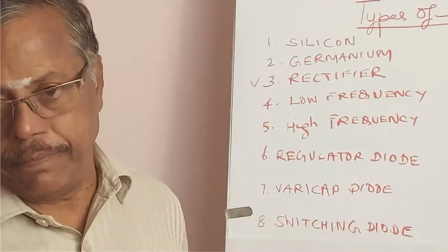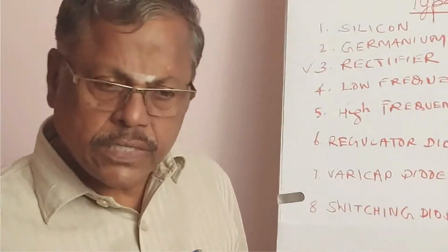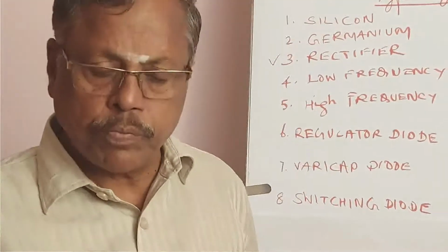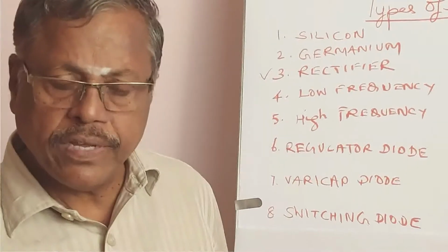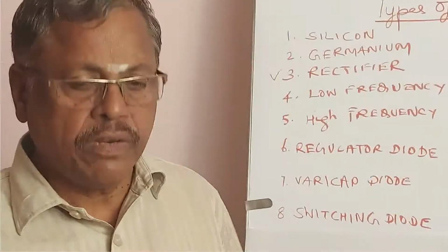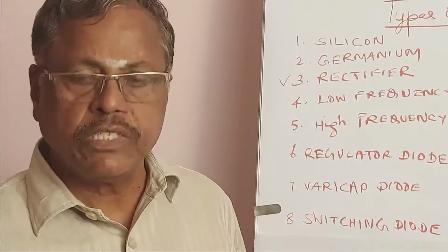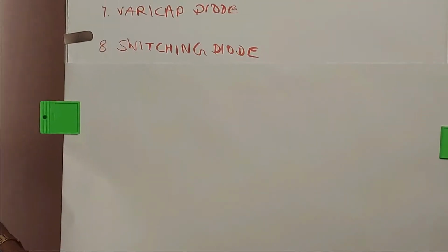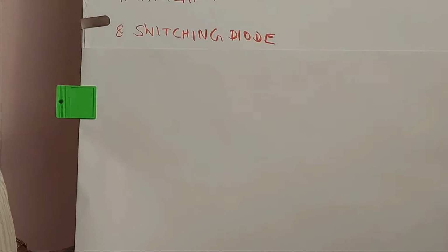They form a capacitance. Every diode has an internal capacitance. This capacitance is normally small when forward biased. This capacitance is going to be large when reverse biased. Therefore, according to the depletion region distance, the capacitance can be different.